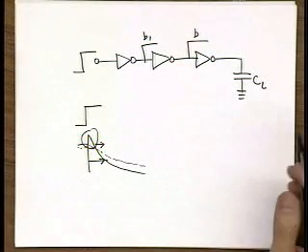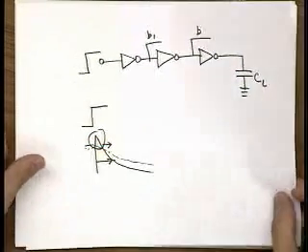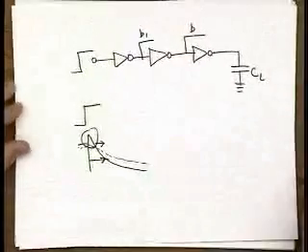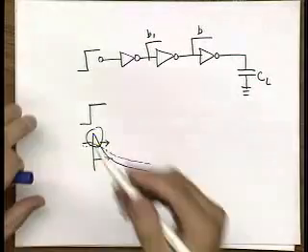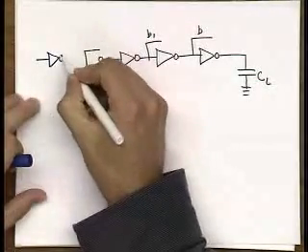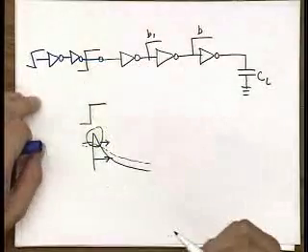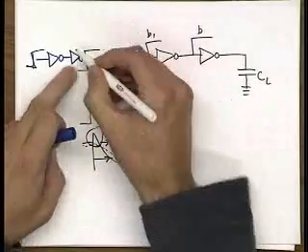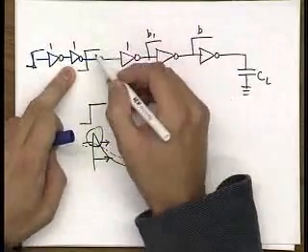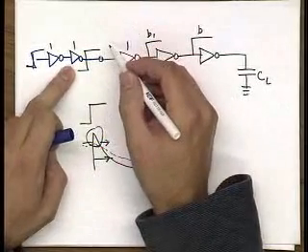So to create a realistic environment for your HSpice simulations and to simulate the real world environment, what you need to do is add a couple of stages to the input that will shape up your signal slopes. So what you would do over here is just add maybe 2 buffers. That would be enough. And then you can drive this with the ideal step function. So over here, you have 1, 1, and 1. So you would have a pretty realistic input waveform slope for your delay analysis.